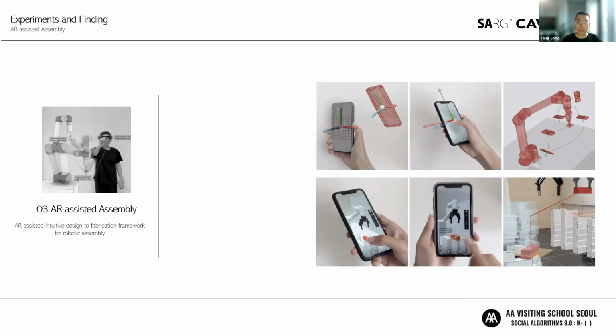For example, in this case, the trajectory is the movement of the robot, and the command is for the end effector gripper to close and open to pick and release the bricks we need. In our system, the user can use their smart device or even their hand gesture to set the trajectory planning points, the trajectory control points, to tell the robot where it needs to move.